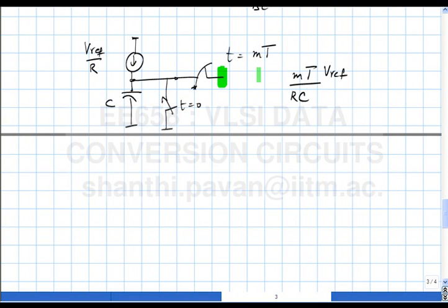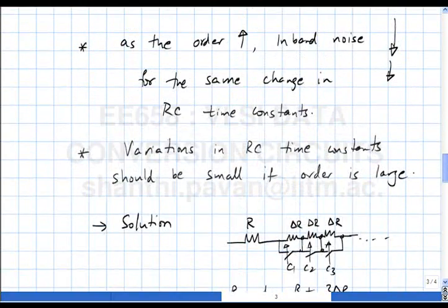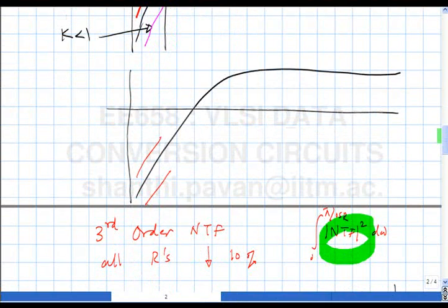Some techniques exploit the fact that the way the quantization noise is shaped in the loop depends on RC. For example, if the in-band gain reduces, what do you think will happen to the out-of-band gain? It will increase.